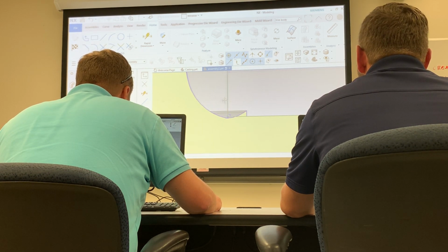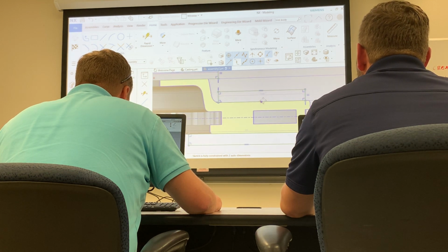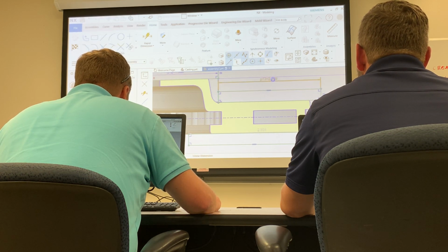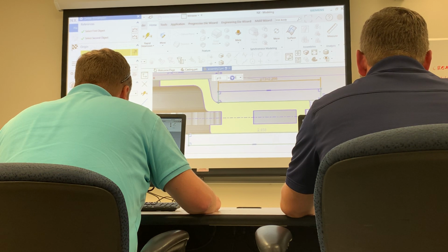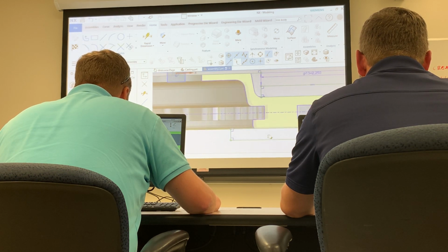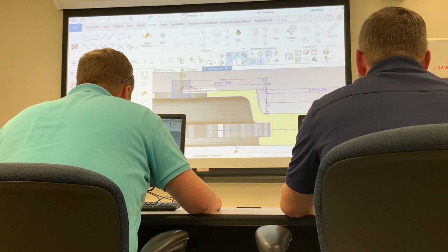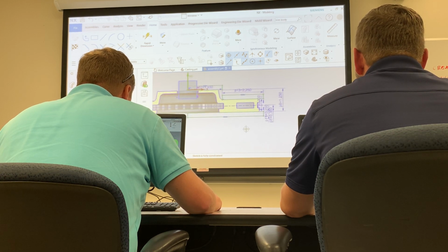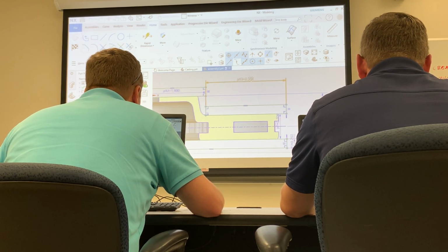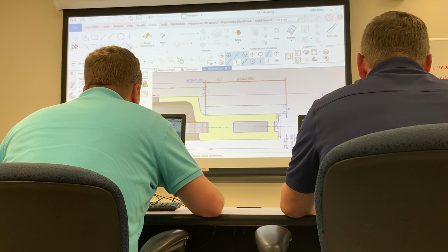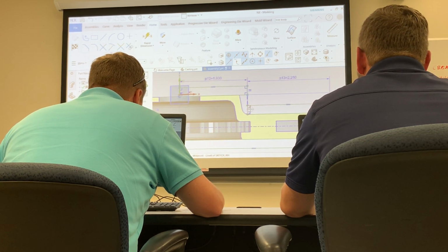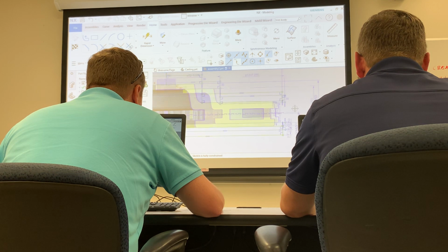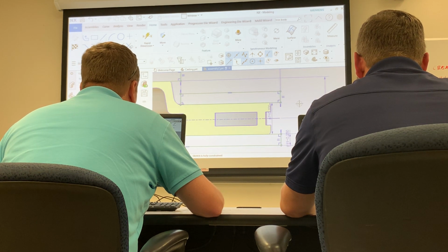So now it's not going to move left or right. That's one of the most important things I need to figure out, make sure that stays. This needs to be a little bit bigger. You stretch it out and see how much bigger. 2 1/4 looks good. And I can just make this lie on that same y-axis too. No harm in that. So I don't have a whole bunch of extra dimensions. But see, this dimension, yeah, it actually has some meaning. At least this 1.93 is holding this where it's not going to get shifted out of position. And these are going to be long enough that they don't get cut.